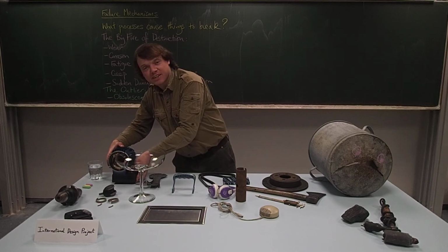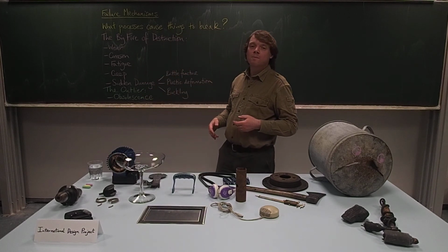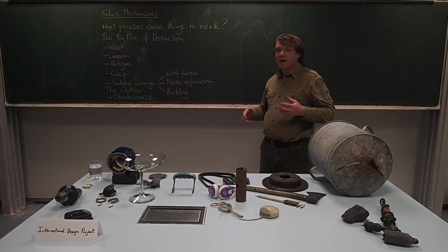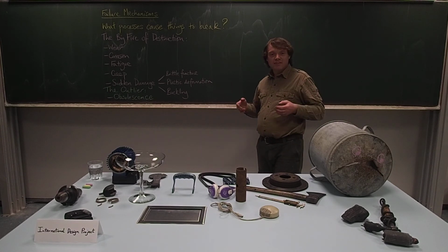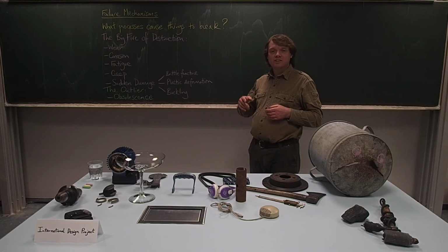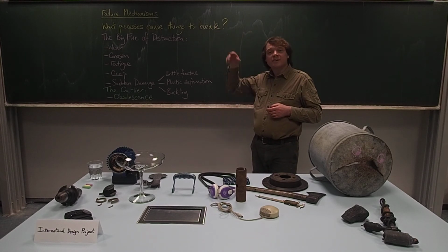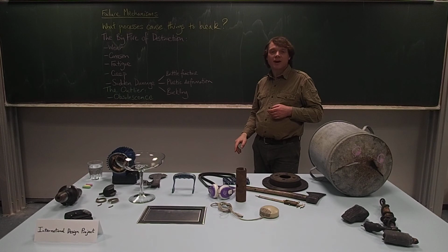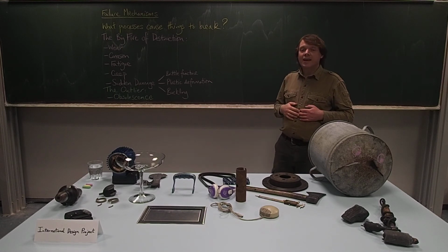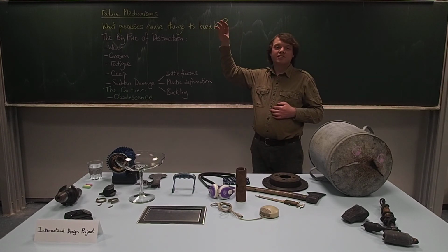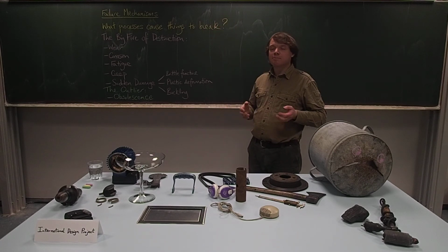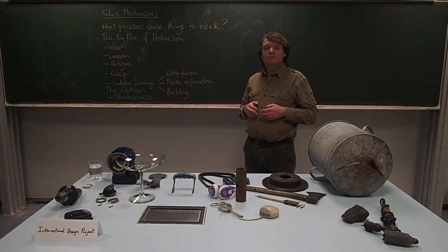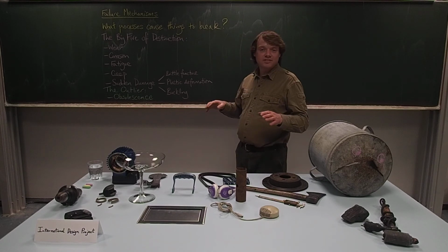Another example would be a wind pump. Now, in lots of places in Africa, and I think also the big open farming areas of the USA, it's quite common to use a small wind turbine to drive a pump under the ground to irrigate a farm. And these have some kind of gearbox on the top of the column, and these are usually a very simple gearbox, and they don't have fancy oil seals or anything.